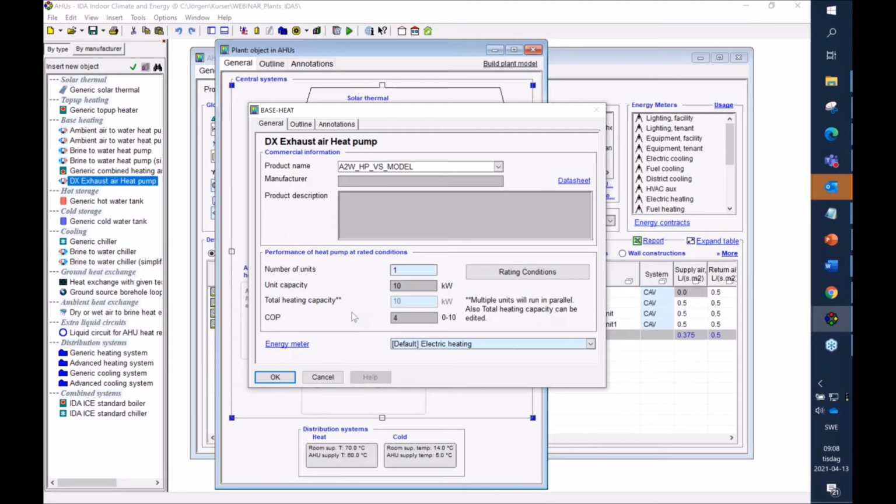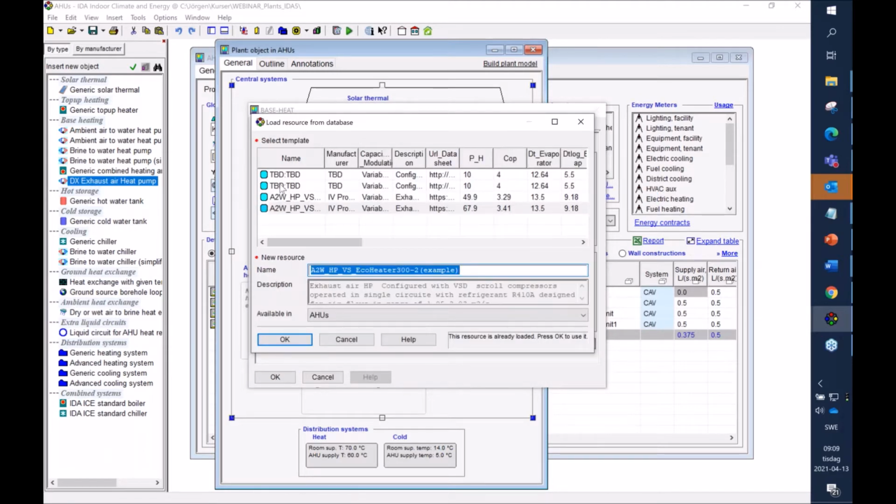So we use that, and then we use optimization to create an entire model, including the evaporator and condenser. So it's not just adding the polynomials, it's a bit more work, but not very much. So we will have a database of such heat pump models.